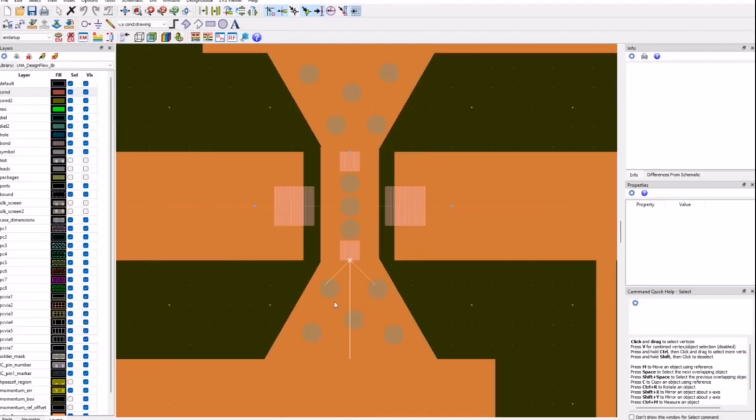And this is the place where my terminal, my emitter or my source will come. You can see I have a good amount of vias there to fuse the emitter or the source directly to the ground. So you should have no hesitation in doing more via holes here.